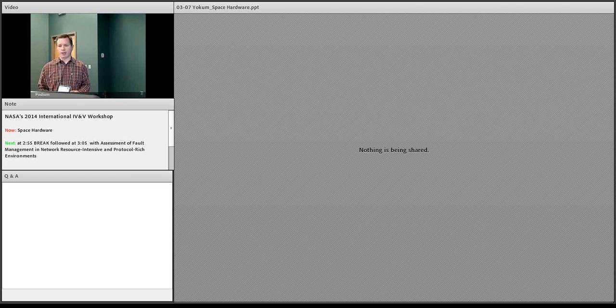Performance. This is probably one of the lesser of the problems, but running these in real time can be difficult, and that is because, again, we're running assembly instructions. That's what we're getting from these flight binaries. We're pulling out the assembly instructions and running them, but we have to do that for every single chipset that's in the model. So we have to run ISIM CPU, spacecraft CPU, the 1553 clocking CPU. All this has to be run in parallel in one host CPU that also has whatever that host operating system is doing and everything else. So getting up to real time can often be difficult.